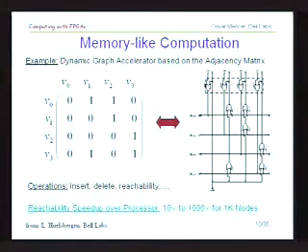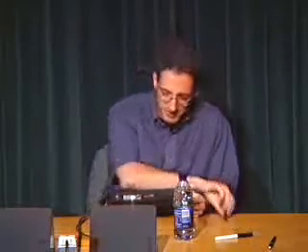The speed up that was obtained here is in the range of 10 to 1,000 times. And the main bottleneck here is really the size of circuit that you can put in an FPGA, and the size of data structure that you can therefore put in there. So after you exceed the size of the FPGA, the problem requires some tiling and partitioning of the initial problem, and that then reduces a little bit the potential benefit that you have.